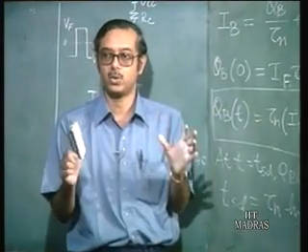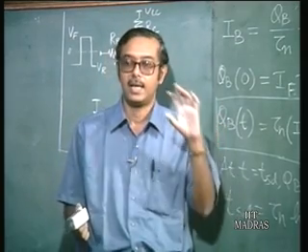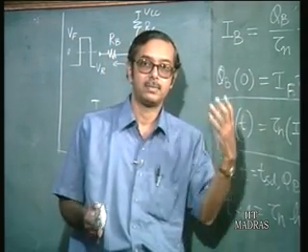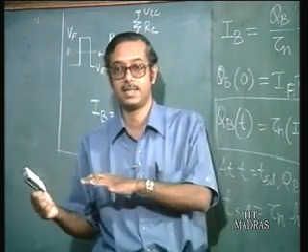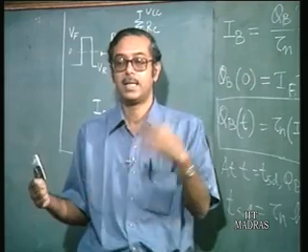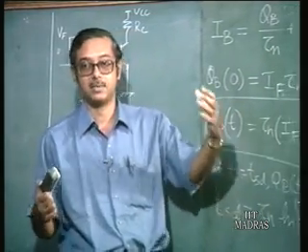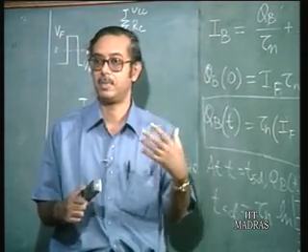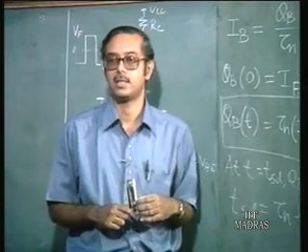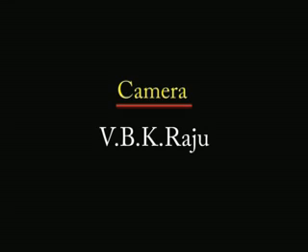Okay. So, that gives us a total picture of the different delays involved in switching the transistor on and off, and one must really appreciate this, because if you want to compare between the different circuits, how fast is one circuit compared to the other, that is mostly due to the different mechanisms for removing base charge or creating this base charge in a bipolar transistor. So, we shall take up again in the next class.